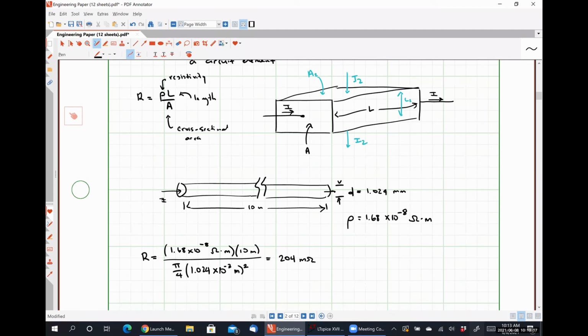Yeah, so the smallest resistor that you guys used, I believe, was around 200 ohms. And you used that in an LED circuit in order to limit the current in the LED circuit, but make the LED shine as brightly as possible. So that, let's call it a 200 ohm resistor, is actually 1,000 times larger than the resistance of this particular 10-meter long section of wire.